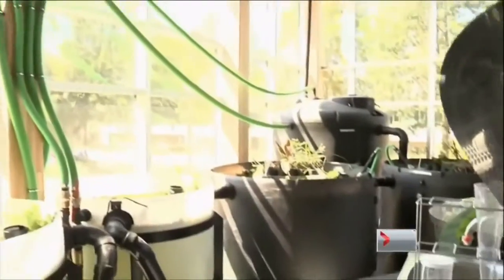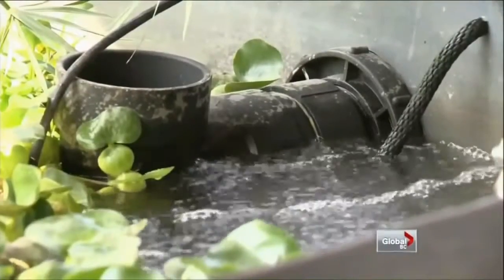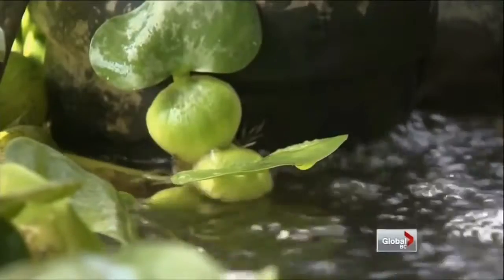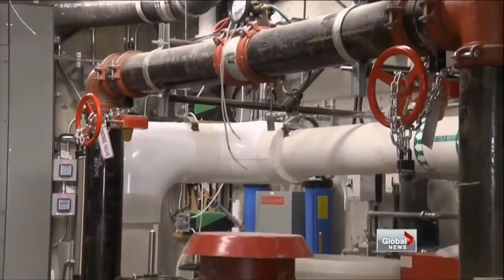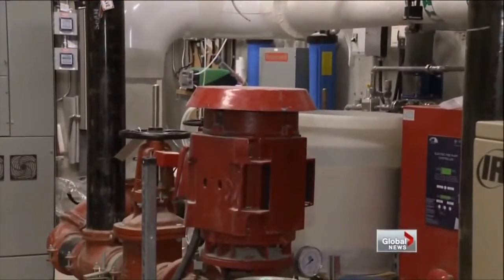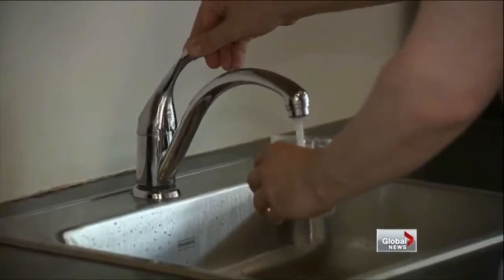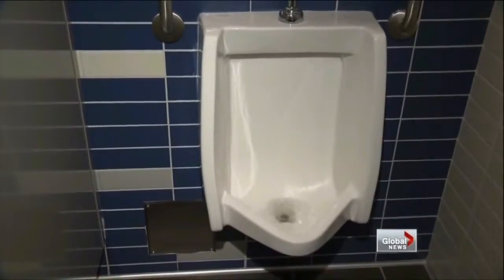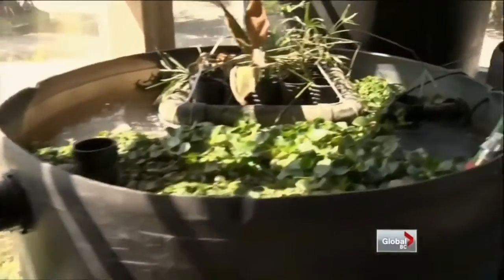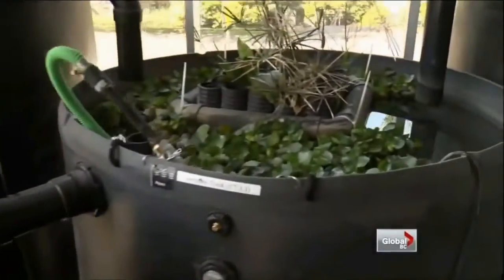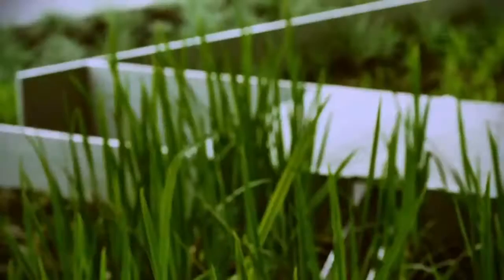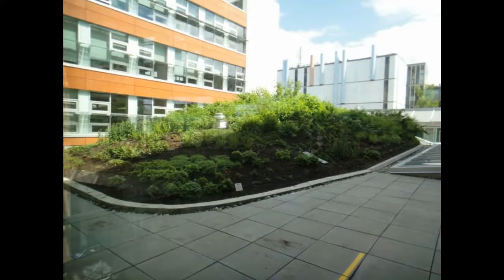No water from rain or sewage leaves the SIRS building. It is all directed to either the water storage tank or the solar aquatic lab for treatment. The water storage tank located in the basement of the SIRS building holds about 100,000 liters of rainwater that is filtered and kept for potable and non-potable use. The solar aquatic lab uses plants to treat wastewater, while the plants also grow from the nutrients contained in the sewage waste. The reclaimed sewage water is then used for irrigation of the green roof.